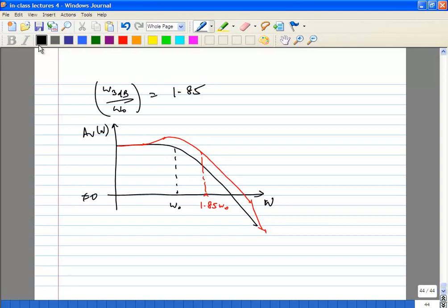So you have managed to get an increase in the bandwidth, but now you have a problem. Your magnitude response is actually peaking. What that means is you have different gains for different frequency components, and you don't want that. It turns out in this case this is almost 20% peaking, approximately 1.5 to 1.6 dB. There are a lot of applications where you don't want that. So what you may want is a maximally flat response for magnitude.